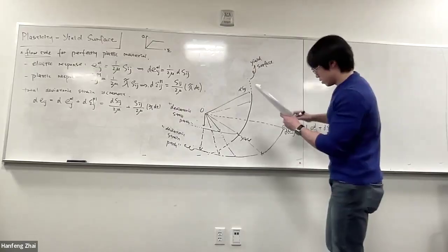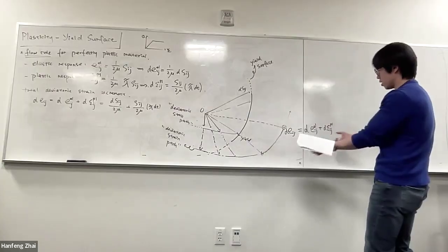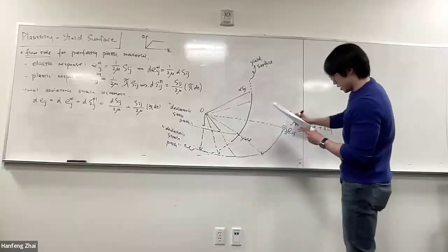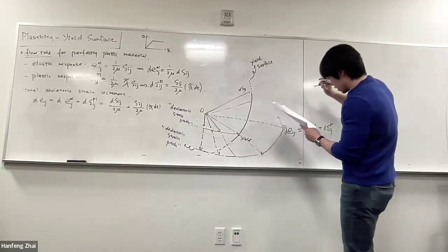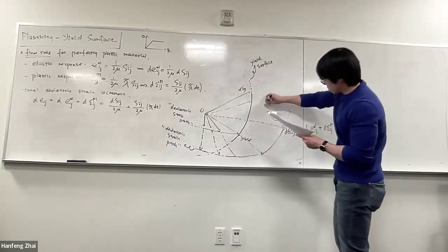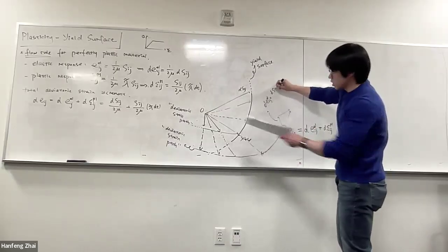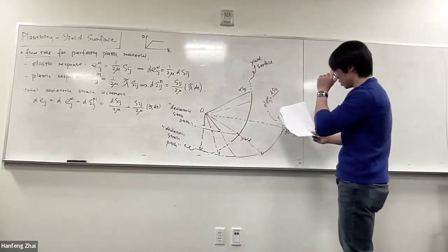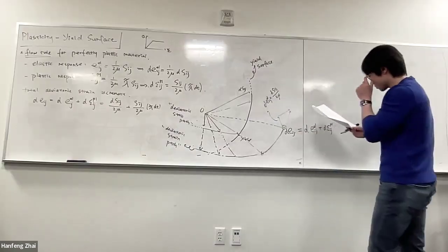And by construction, this formula we know is a vector operation, right? So if this is pointing to de_ij, then this can be decomposed into this as de_ij elastic, and this will be de_ij plastic, right? So de_ij elastic is ds_ij, following the definition, making a step change of the deviatoric stress divided by the shear modulus.